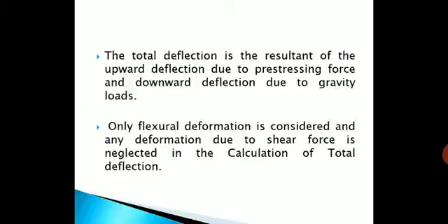All the deflection is downward itself. Whereas in PSC members, the prestress force produces a deflection which tries to counterbalance. In my previous lectures also I have always stressed the word counterbalance. Prestress force is that force which tries to counterbalance or react to all the actions produced by the loads.